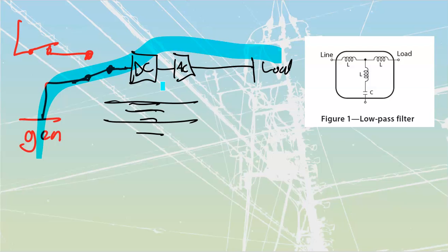They are going to be large, they're going to be expensive components, but they're going to be good for our over voltages and for our under voltages, right? That's what they're designed to do. They're not designed to take out any sort of harmonics. If I need to take out harmonics, then what I'm going to need to do is use reactors, as well as I'm going to have to use my zigzag rated transformers or my K-factor transformers.